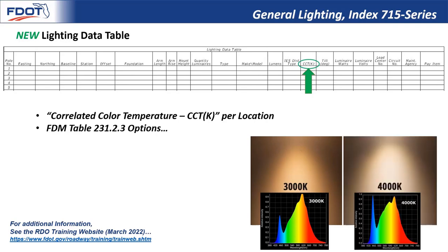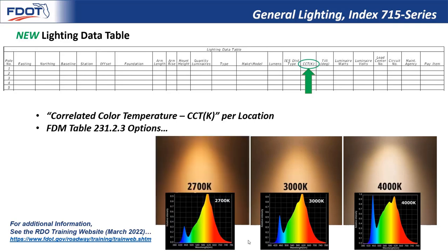And then next is the 4000K option, which offers that very white light that almost resembles the fluorescent lighting. The colors pictured here actually are a little bit warmer than the results that you get in the real world. So the actual results are a little bit whiter than what's shown here. But this 4000K is only used in a few very specific cases in urban and suburban contexts with the very high design speeds. And last, going even a little bit warmer than our standard 3000K option, 2700K is available for design speeds of 35 miles per hour and less.